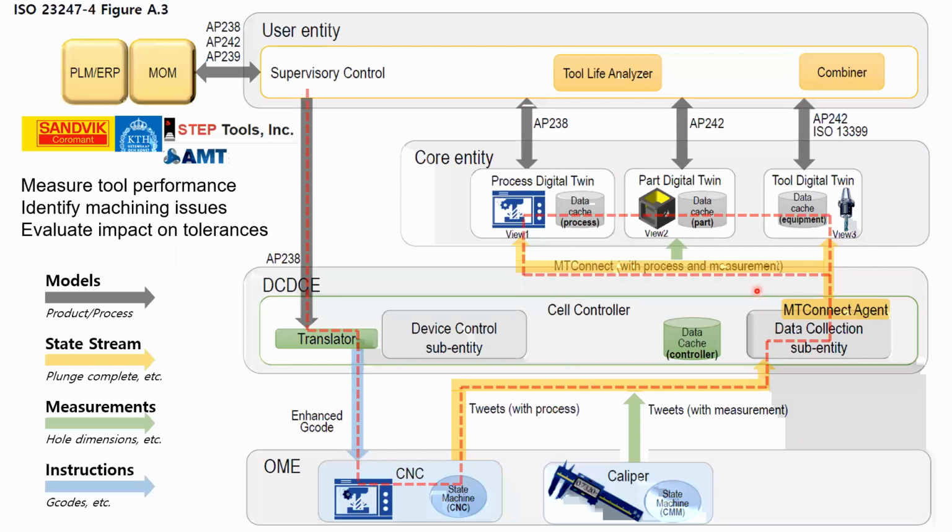It has access to the full MTConnect sensor data, now in the STEP-NC context. And this demonstration will use feed override as an example. So we can see how we can relate the information back to the process step being executed and also the feature being executed. What we are not going to show is the measurements, but that was shown in use case 2, and it's a similar flow, where measurements can then also be related to the feature that you have measured.